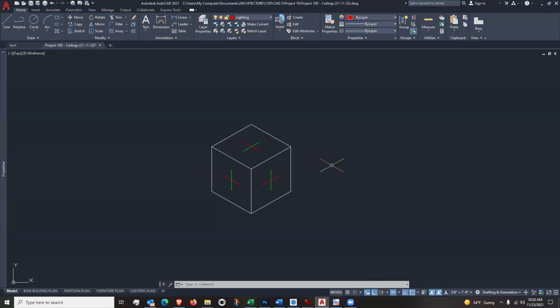So that means I am drawing kind of like in isometric plan. At top view, I'm looking down at this surface here. My F5 key is a way for me to toggle between my views. So if I just toggled now, I am in isoplane right. And in fact, I can see it right down here above my command line. I am in isoplane right.